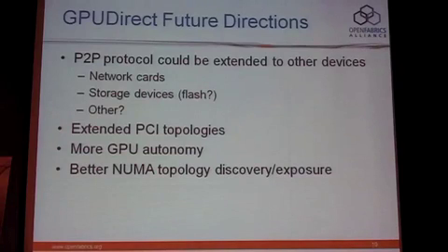But it's pretty specific to our hardware, and I don't think it's really a standards track. It goes over PCI Express, so it is a peer-to-peer busmaster transfer, but you have to layer a protocol over that. GPUs actually are MMU backed; they're not just memory sitting out on the PCI Express bus.